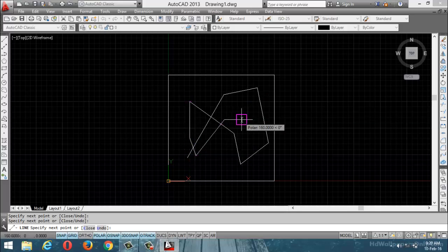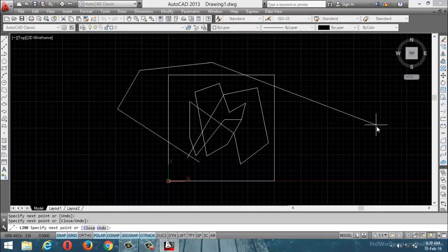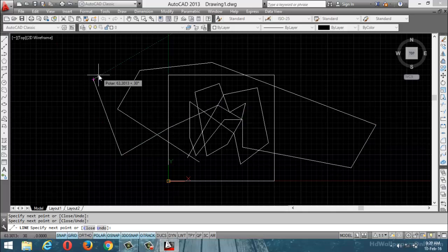I am going to select the points. Okay. Now I am going to click in this area. What happened? No design. Not possible. Why? Limits is on condition, which means the design is possible only within the limits area. Then again I am going to set limits off. Again I am going to design the line. What happened? You can design in any area, within the limit area and also without the limit area. That is about the settings.